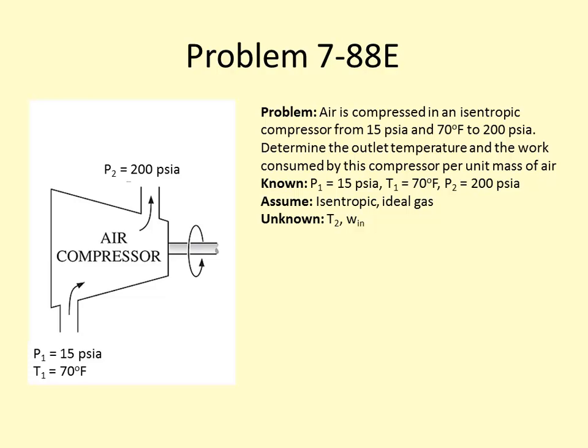Okay, so adiabatic, Q in, no Q out. We don't have any work out because it's a compressor. We're putting work into the system. So work in is equal to m dot times H2 minus H1. We're also not given a flow rate in this problem. So if we divide through by m dot, then we have a lowercase w is equal to H2 minus H1. And again, we're using the approximate approach, so this is equal to C sub P times T2 minus T1.